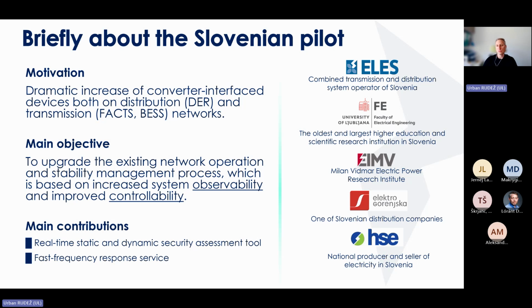So this is why the 2 main contributions of the Slovenian pilot can also be split into 2 ways. The first one is to develop the real-time static and dynamic security assessment tool, addressing the observability problem. And the second one, develop the fast frequency response service, which tackles the controllability problem.